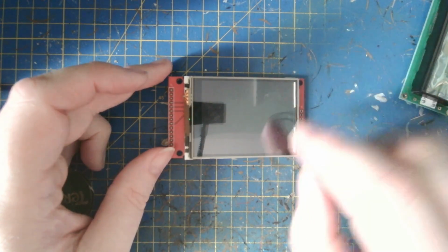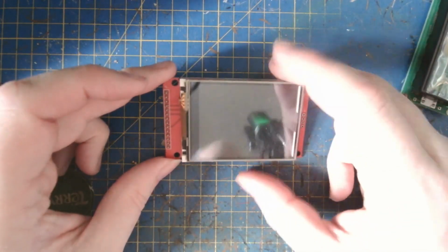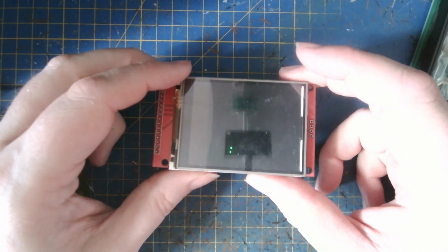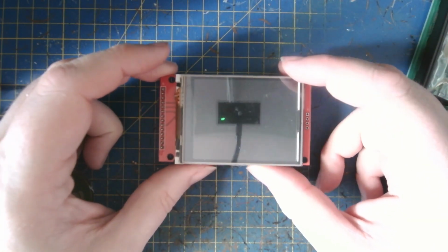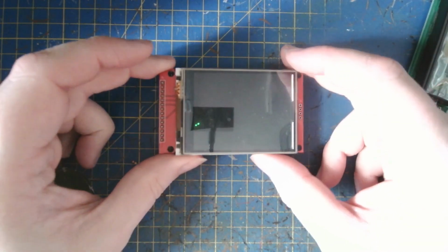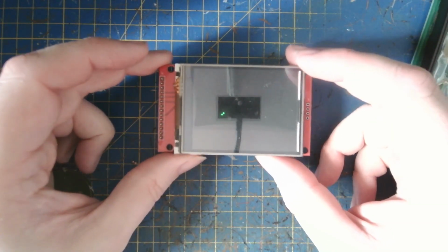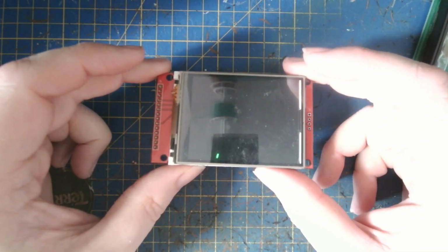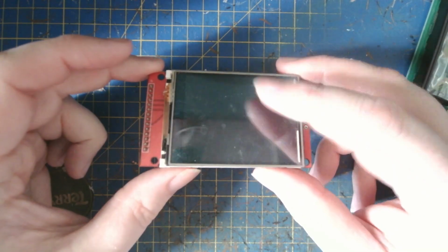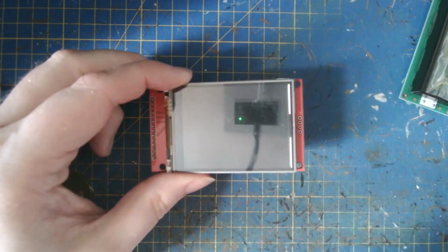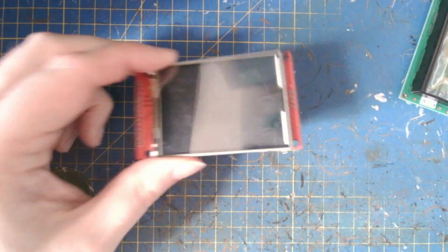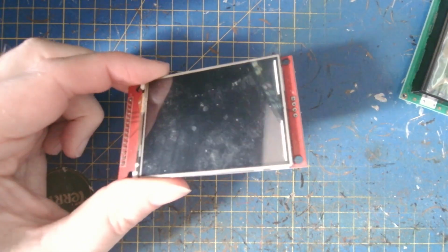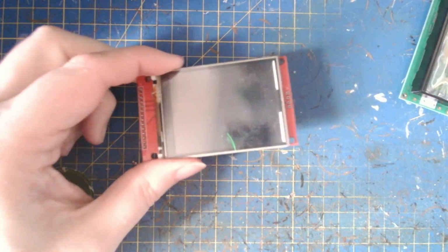Just displaying text, you can tell it, write out text. You can get quite a bit of text on this. They're not brilliantly clear to read. They're not bad, but because it's got a backlight shining through something, you have issues with viewing angles. These are pretty good if you've got something like an ESP32 or the ESP8266 or something similar to that, where again, like I say, you can use it as a touchscreen as the complete display. I've used a number of these in the past. They are actually quite nice. They're quite useful. They're not that expensive. 7, 8, 9 quid, something like that for one of those.